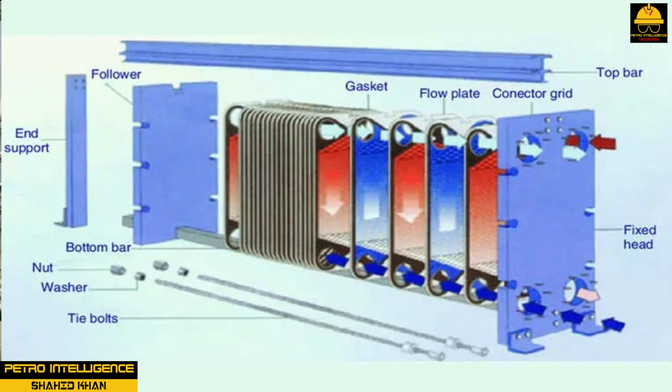It provides excellent high heat transfer. Plate and frame heat exchangers are compact and easy to clean. Operating limits of 350 degrees Fahrenheit to 500 degrees Fahrenheit or 176.66 degrees Celsius to 260 degrees Celsius are designed to protect the internal gasket. Because of the design specification, plate and frame heat exchangers are not suited for boiling and condensing. Most industrial processes use this design in liquid-liquid service.